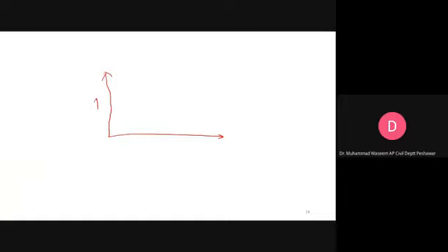On the x-axis we have some depth to thickness ratio, and on the y-axis we have moment, and we have this type of curve. We said that this is compact, this is inelastic buckling, and this is elastic buckling. So this is the compact section, this is the non-compact section, and this is slender.